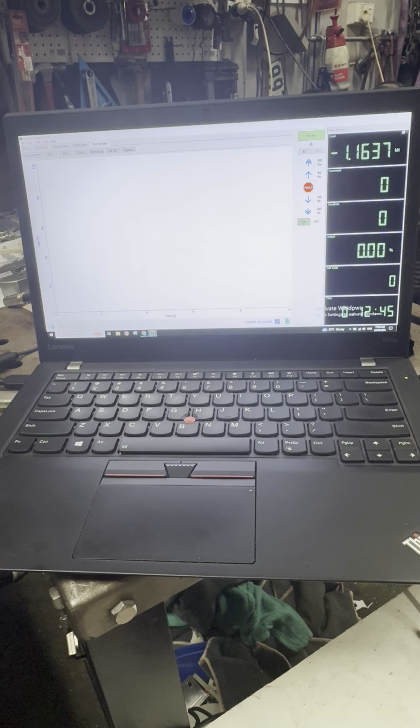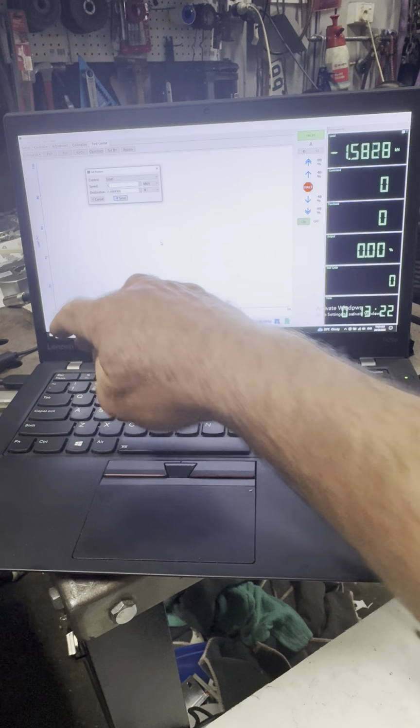Over here up the top, we've got different controls that we can engage. We've got some commands. We've got PID features that generally nobody will work with. We've got a position control here. We can select the speed. I'm going to select kilonewtons a second. I'm going to put, let's say, 1 kilonewton a second in there.